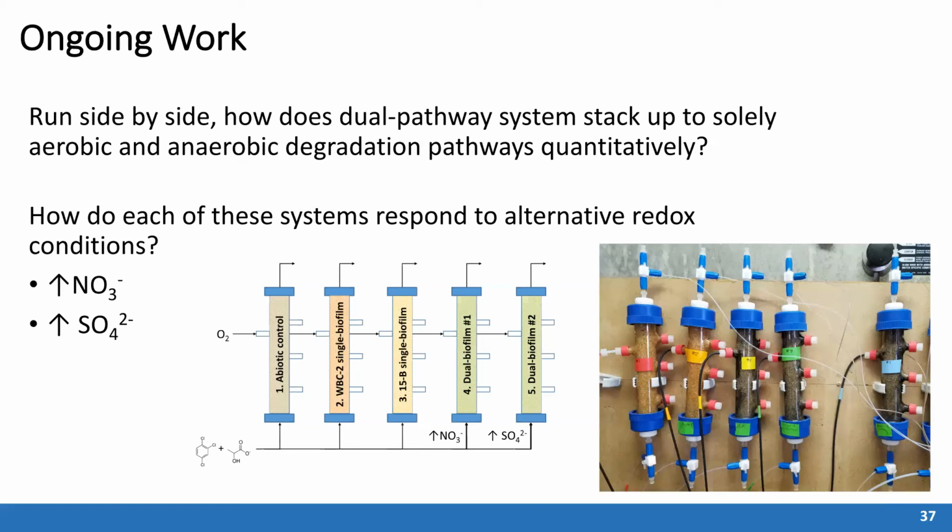And we don't know that, but that's one reason why we want to try this, because the field site is an estuary or has the ocean water influence. So there is some sulfate in the surface water. And so if you get the tidal action, you might get some sulfate into the sediment. And then there is some nitrate around too from agricultural activity in the region. And so we're just looking at those electron acceptors and their influence.